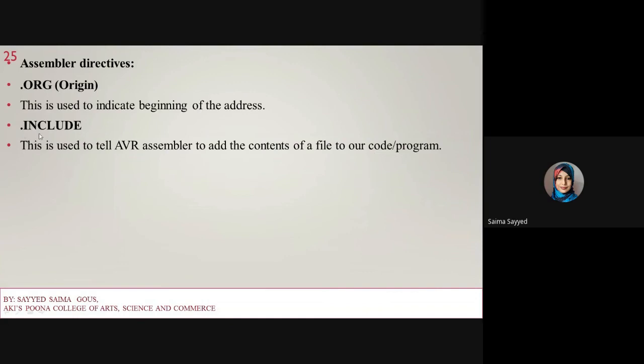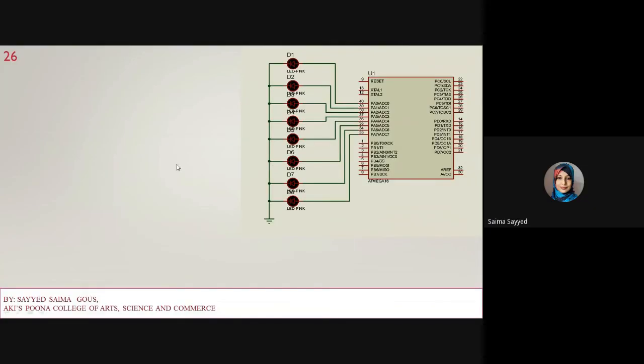Every program starts with this .include and .org. If you are using ATmega16, you write m16def.inc. And if you are using ATmega32, instead of 16 you write m32def.inc.